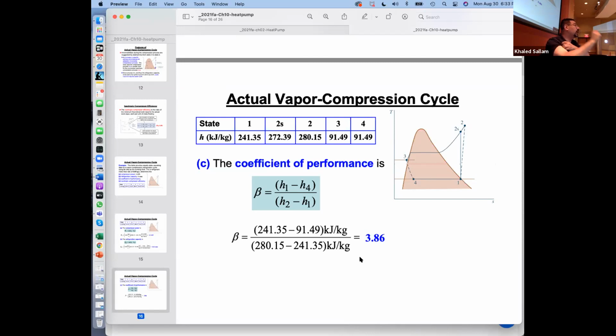Right. So they have to quantify the temperature difference that COP would work at. Because as the temperature difference increases, the COP will decrease. So did they get it for COP at 0, for example? Like over 0 temperature difference? Because you have to go 5 degrees down and 5 degrees up, so then 10 degrees. That would be the best COP they will have ever in their life. Right? When you are cooling the air in one room, ambient air, and you are heating the ambient air in the other room. So same temperature.